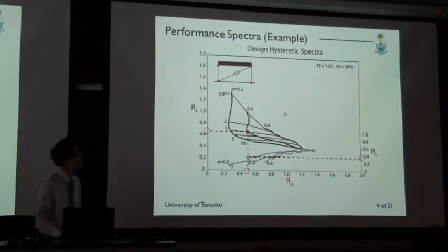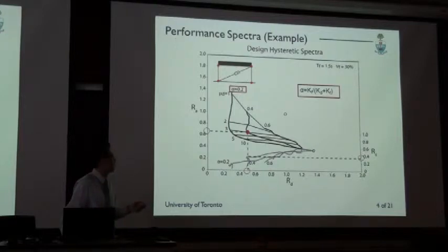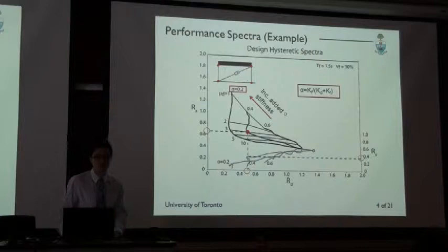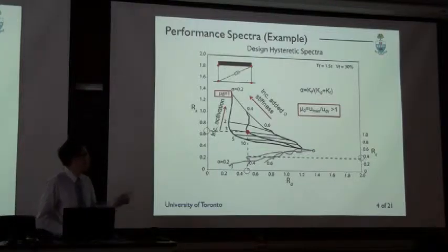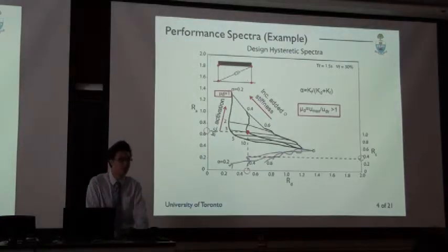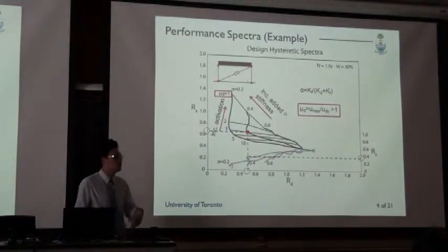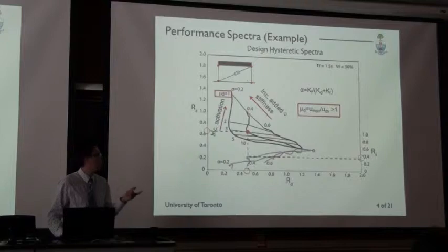Each of these solutions is identified uniquely by damper parameters. In the case of hysteretic dampers, we have a stiffness ratio, alpha, which is defined in such a way that decreasing alpha means increasing supplemental damping stiffness. There's also the damping ductility, where decreasing damping ductility means increasing activation level. So for each solution that you select based on your performance target, you can identify them uniquely using two parameters, which you can then use to transform into an MDOF structure.